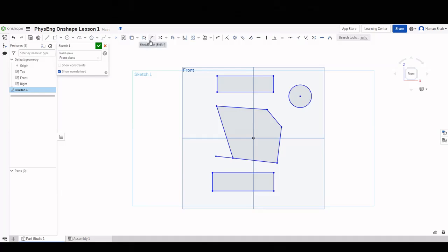Now I'm going to be going into some of the more advanced drawing tools. Nothing like actually drawing, but it's basically just altering stuff that you've already drawn, right? So let's say you've drawn this circle, and now let's say you want another circle around it that's at the same center, right? So what you can do is you can use a tool called offset. It's right here. You click on the offset, you click on the specific shape that you want to offset. We're going to choose a circle, and we can offset by a specific point. And you just enter, and there you go.